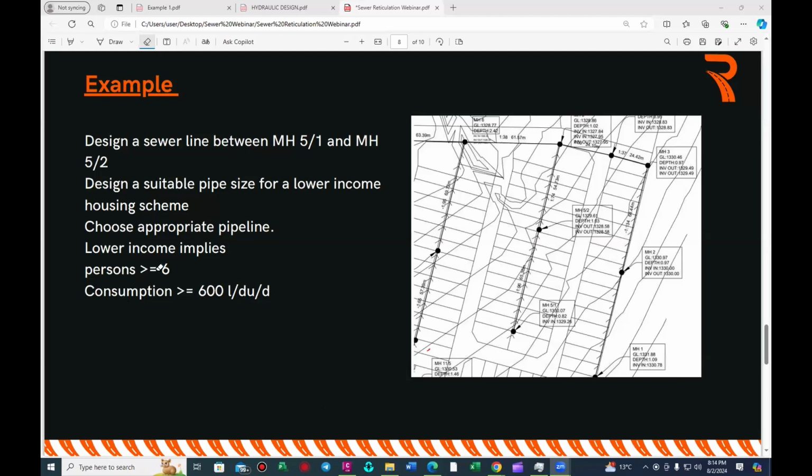I've got an example that I want you guys to really pay attention to, to show you how I bring in my hydraulic design, and how I bring in my Civil 3D aspect. Whenever you're designing your sewer system, you start with what we call a preliminary design, right? You start by laying out the sewer, you start by proposing the pipes, you start by proposing the slope, right?